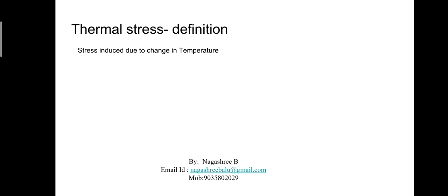So I repeat it. When an object is subjected to change in temperature, some amount of stress will be induced in the body due to the change in temperature. Such stresses are called thermal stresses. Thermal stresses are set up in a body when the temperature of the body is raised or lowered, and the body is not allowed to expand or contract freely. In such instances, thermal stresses will be developed.